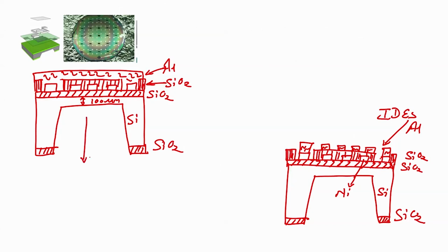So, next step is spin coating photoresist, right. Quickly we will spin coat the positive photoresist. After positive photoresist, we have to perform soft bake. After soft bake, we will use a bright field mask and load it onto this wafer, like this.